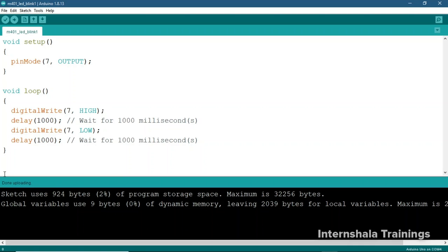The process is simple. I am going to repeat it. You can directly start working with Arduino IDE. Write your code, connect your board, configure the ports and then upload after verification. If you want to see the simulation, first you can go to Tinkercad, do the simulation, download the code or copy the code and then come to IDE and then verify and upload your code.